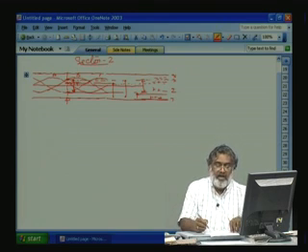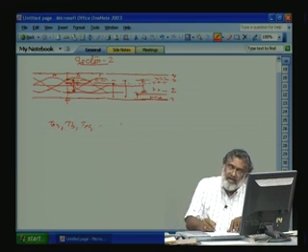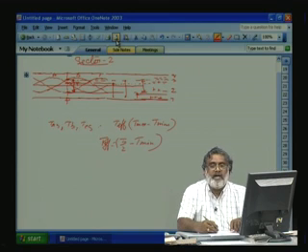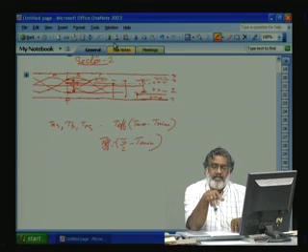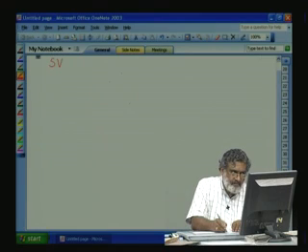So here also the same we can use. We can find out TAS, TBS, TCS. Then T effective is equal to T maximum minus T minimum, of these phases. Then T offset is equal to T0 by 2 minus T minimum. This offset you add, and everything will go to the positive side, and we will get the corresponding gate signal for the top switches of any leg, and for the remaining period in a sampling period we have to switch on the bottom switch. So this algorithm will be very simple. So let us write down the algorithm for digital implementation. Yes, very simple algorithm. So our algorithm for the space vector PWM, we will write now.